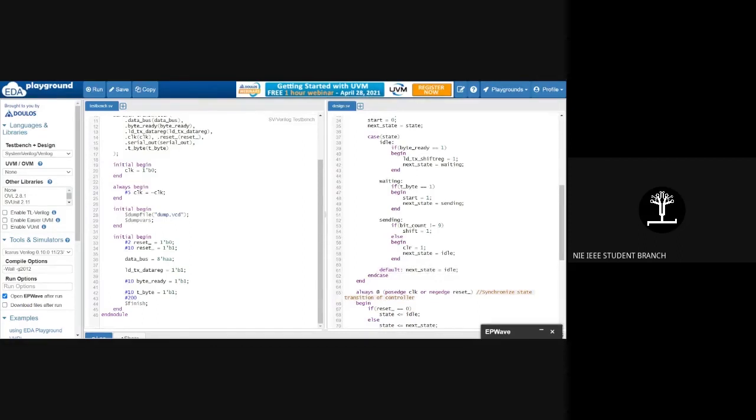Okay, that is one thing. So this was the always block, which I told you, it is level sensitive and it synthesizes a combinational logic. You see, all of this is combinational. Nothing depends on clock, and there's no feedback kind of thing. So this is combinational.